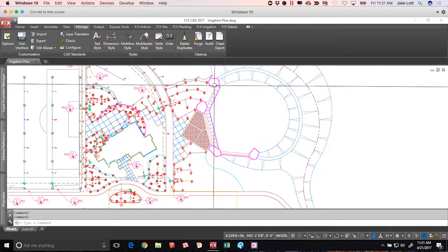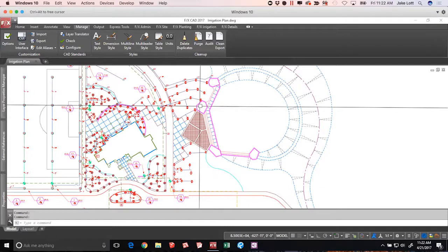I know detaching XREFs and reattaching them can become somewhat of a hassle, especially with multiple changes going on and multiple XREFs and multiple projects. However, even integrating our FXREF tool into the process, I mean, that tool alone on loading XREFs back in is awesome. I love that tool, and being able to just go ahead and detach things and then not worry about UCSs that you're set in and stuff like that. It does speed up the process, but I think you hit it all.